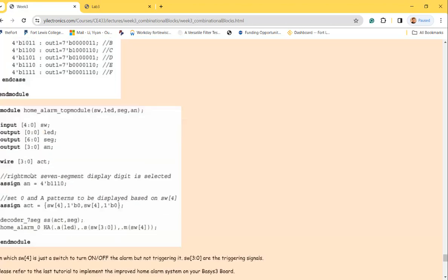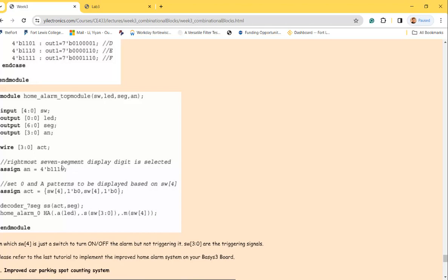It doesn't matter. So all the 4-bit inputs, and it's going to output a 7-segment display code to turn on certain LEDs. It's just a decoder, but nothing else. And the top module is an interface to the FPGA and taking in all the sub modules.